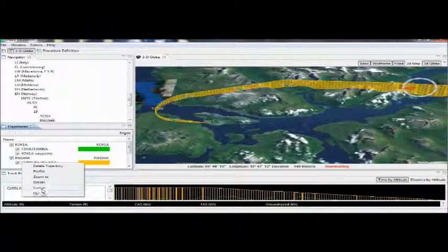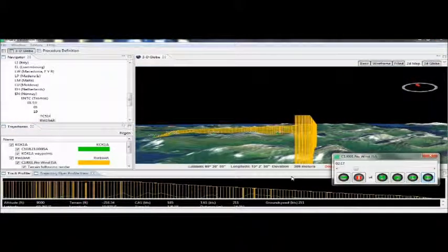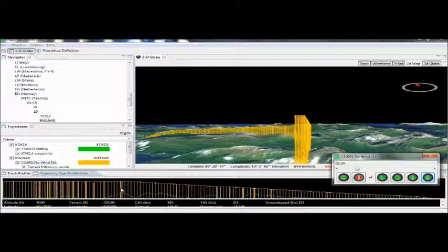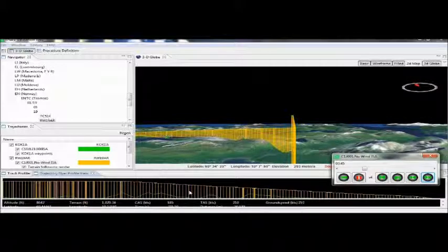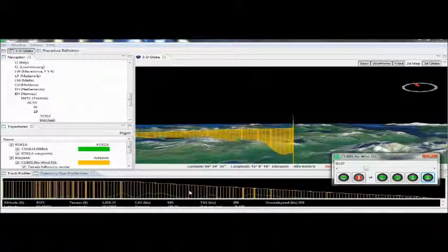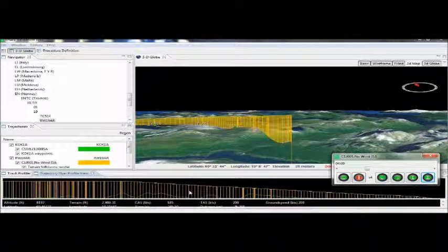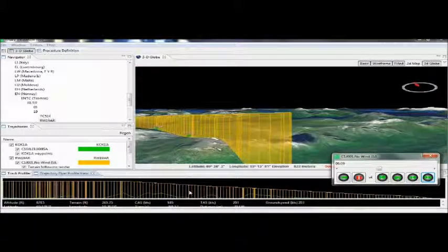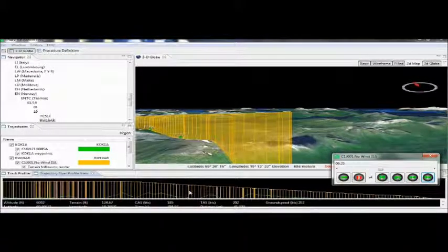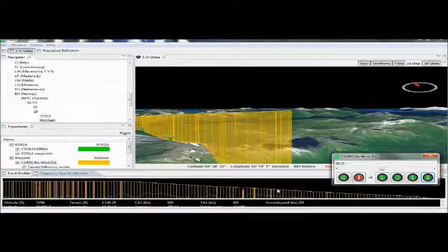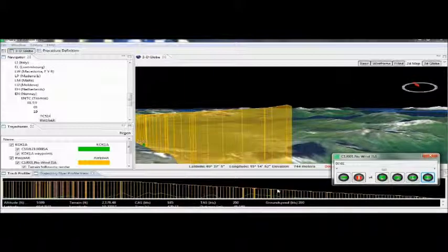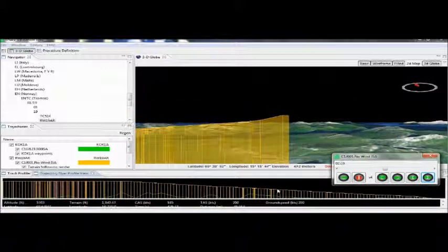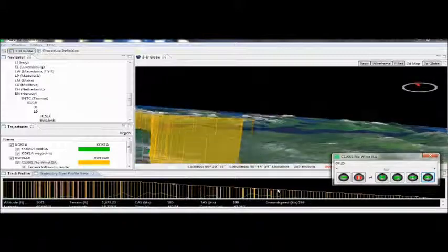One can also fly the profile. We're now starting the approach, and here a small red cross indicates as we're reaching top of descent, and now we start descending. Aircraft briefly arrests its descent to slow down, now maintaining 185, continuing its descent and about to enter the RF turn.